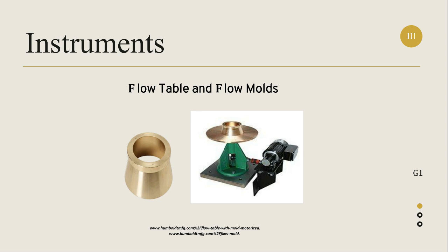Next is the flow mold used to determine the flow of hydraulic cement mortars and cement pastes, conforming to the requirements of specification C230 or C230M.